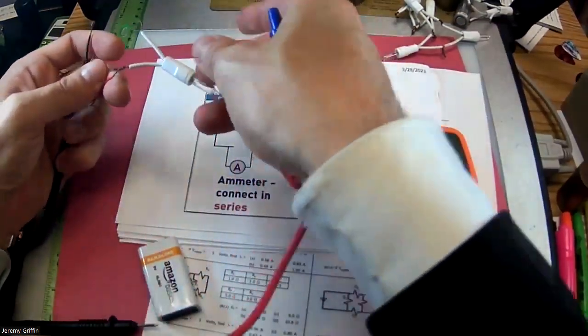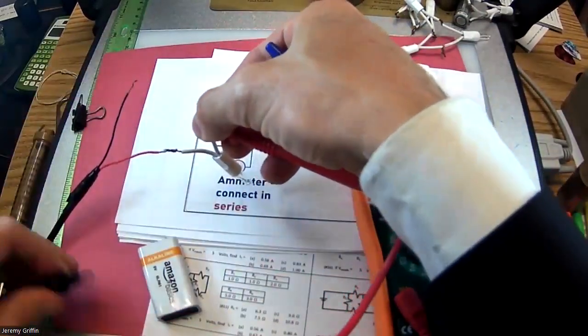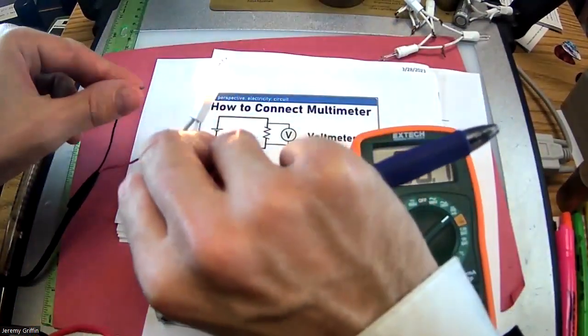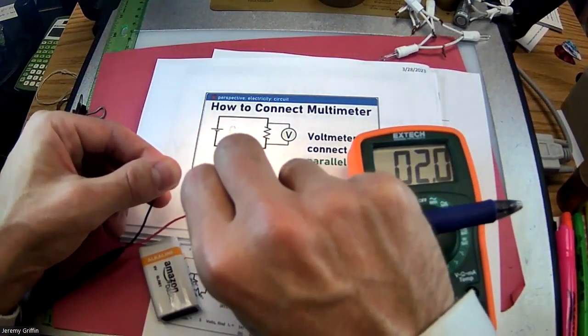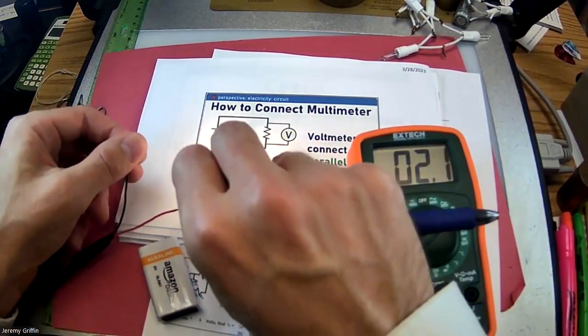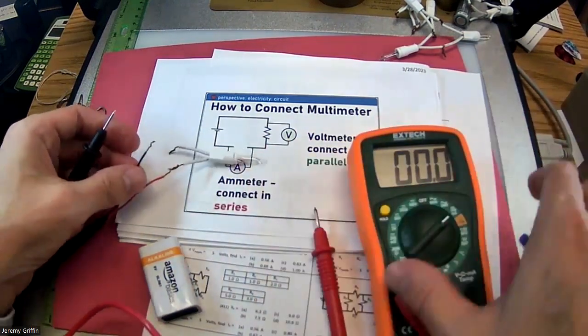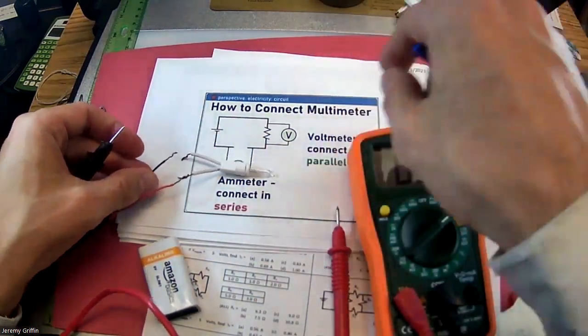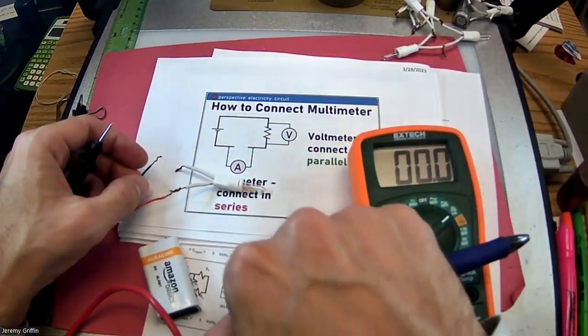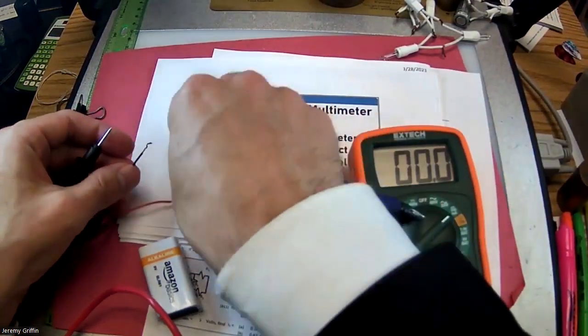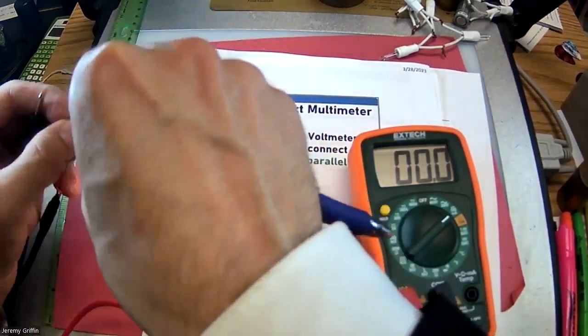So let's see what that is. If I attach the red to the red side and the black side, now this bulb's about to light up. Watch it light up. Boom. Okay. And do you guys see 2 amps? You guys see 2 point something amps? So then you've got 2 amps flowing. Okay. Now, if you want to measure voltage drop, you actually have to measure it in parallel because you're measuring a potential difference. What's the potential difference across this bulb? Okay. And for that, I have to actually make the full circuit.